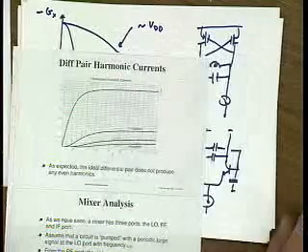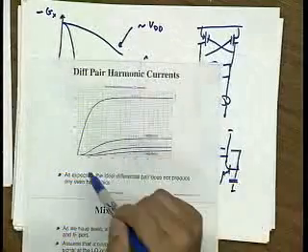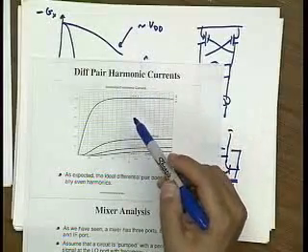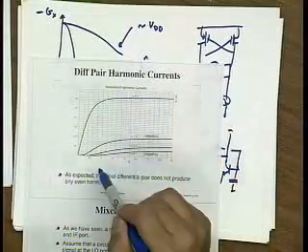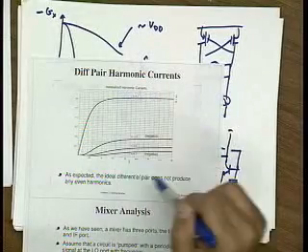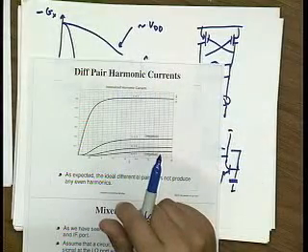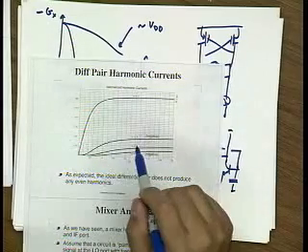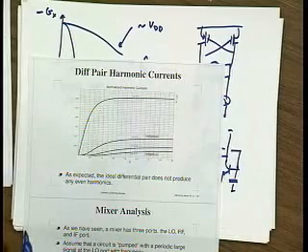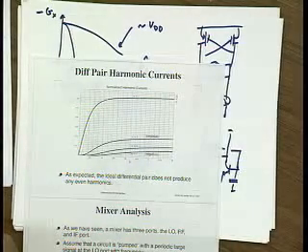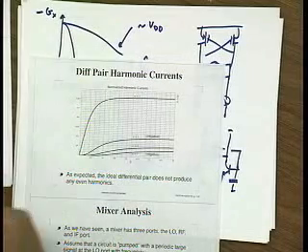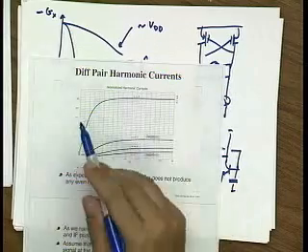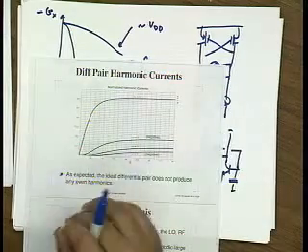And basically, you have curves like this, which is a normalized harmonic currents of, let's say, a differential BJT diff pair, versus B, the overdrive voltage. And you can generate similar curves from MOSFET devices. Interesting point is that these curves are compressive. And that's because naturally a BJT will compress, right? Because the current is fixed. The sum of the currents has to equal the bias current. So you don't have to do anything special for a bipolar or a MOS differential pair to compress.